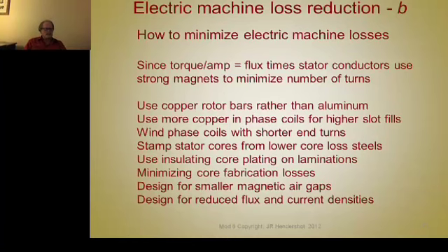Now at low torques, low currents, that's probably not a problem on the OD because the flux density out there is low. But during times of peak torque, when the current is high, the flux density out there could be pretty high, so you can have additional heating right at the OD where the laminations are shorted together from the grinding process.